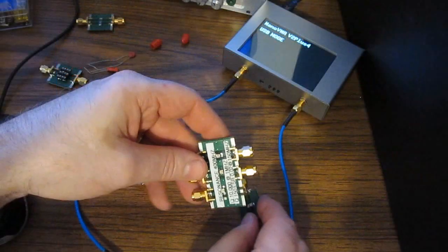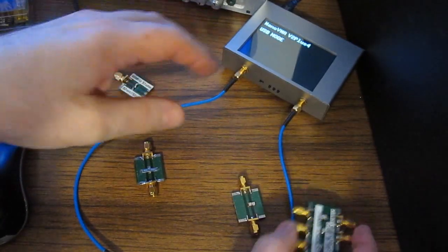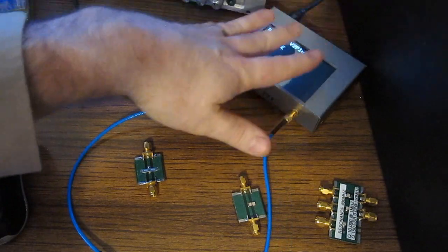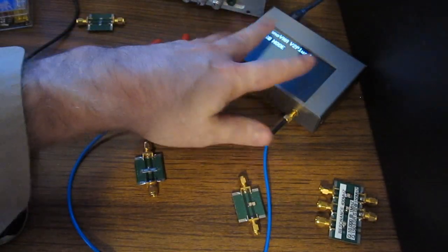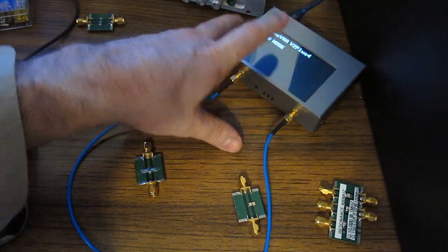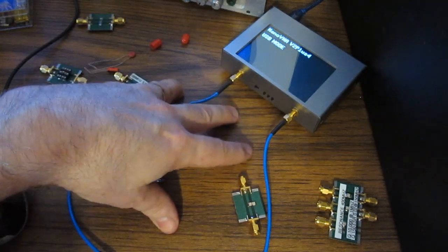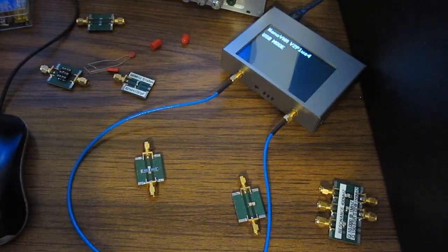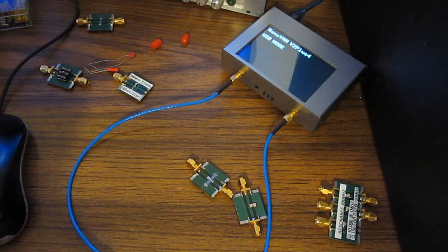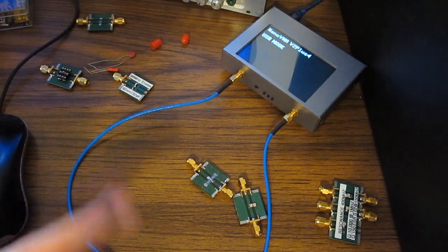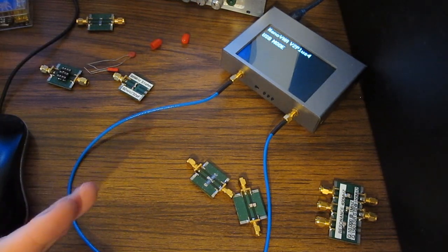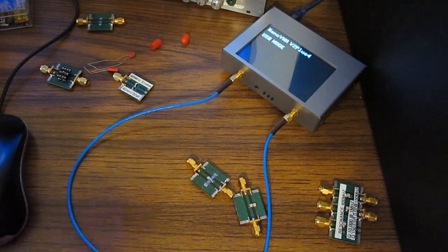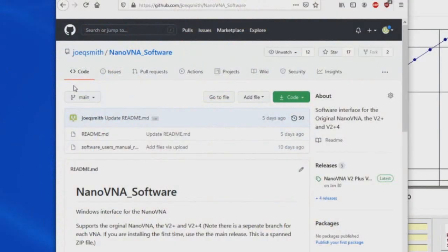Fairly close. Now normally if you're making measurements like this, you're probably not using the Nano. This thing actually has quite a bit of noise, so if you wanted to measure something even lower than this, let's say down to a milliohm for example, you'd probably want more data, so you zoom into that resonant point and then you do some sort of filter or averaging on that data to try to get a more precise measurement.